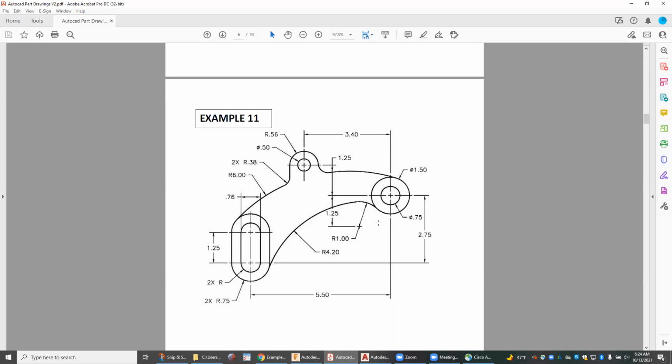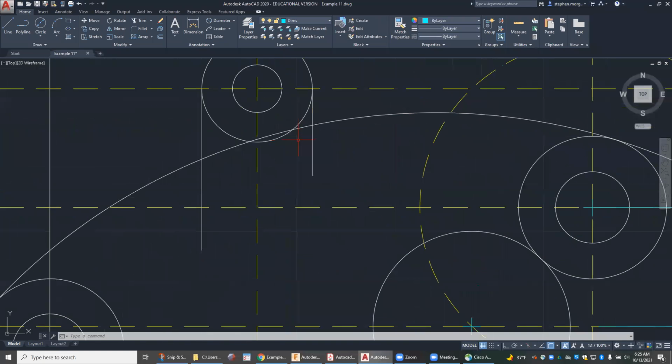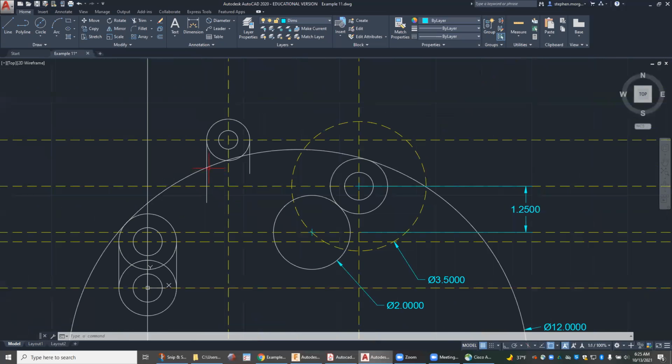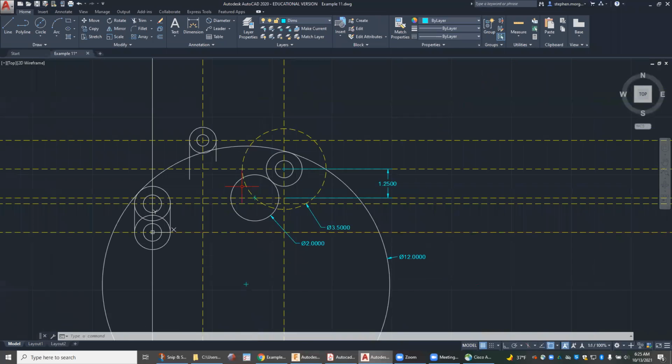now the tricky part is going to be this section down here. Oh, and if you're not familiar with the tangent radius circle, go back and look at the previous video as a refresher. I go over that quite a bit. And these here are just fillets. So once you bring your lines down, right in here, you can trim these and trim these, and then grab your fillet tool and create a radius between these two. So that would work as well.